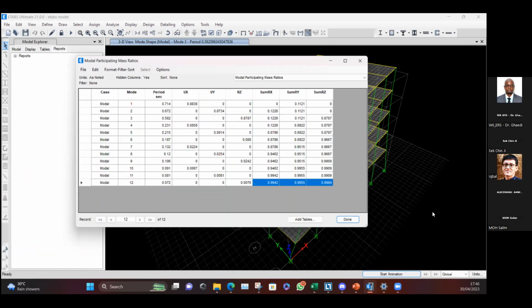For example, maybe you have something like this. Here you have the shear wall, and maybe here you have another, let's say, core wall, something like this. And then definitely the center of rigidity will move somewhere. For example, assume that the center of mass is somewhere here. Sorry, the center of the pillar is here. And then just by adding this wall and this wall here, you are moving the center of the mass to somewhere here, and this affects the mass participation factor under different modes.